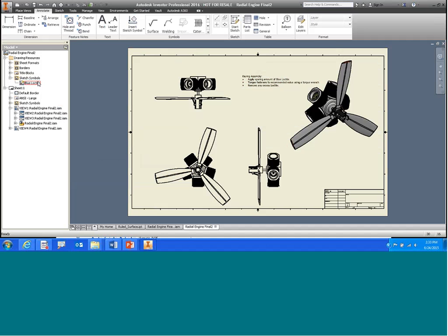Okay, one question I get a lot of is, so my system administrator makes a change in the source library. Is my drawing going to always update that? And unfortunately, it does not do that. You would need to go in and download the blue Loctite again and add it to your drawing. So there's no associativity once it's been pulled from the library.